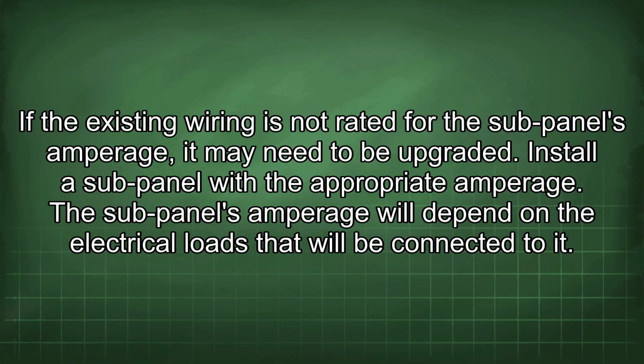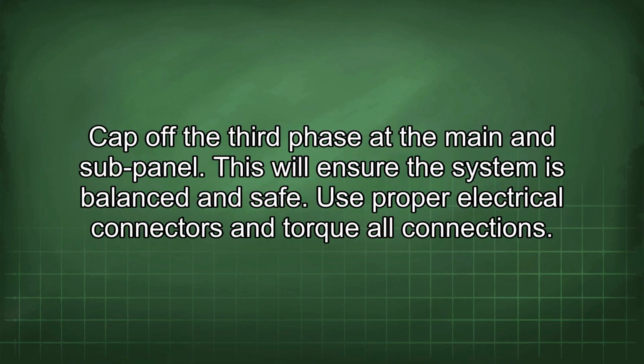Install a subpanel with the appropriate amperage. The subpanel's amperage will depend on the electrical loads that will be connected to it. Cap off the third phase at the main and subpanel. This will ensure the system is balanced and safe.